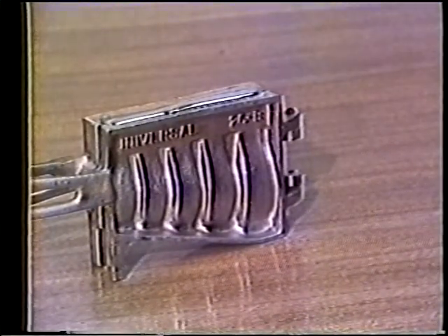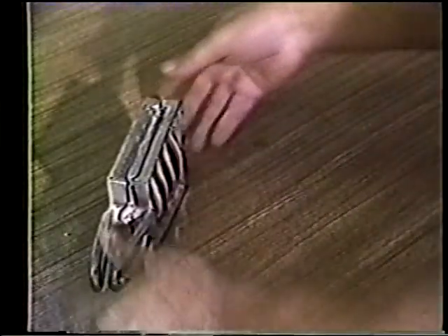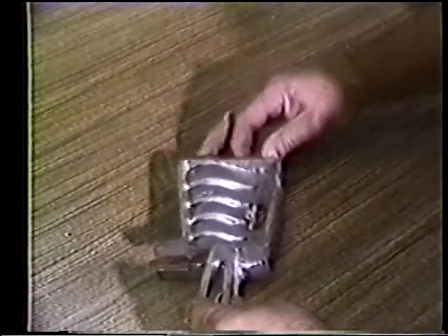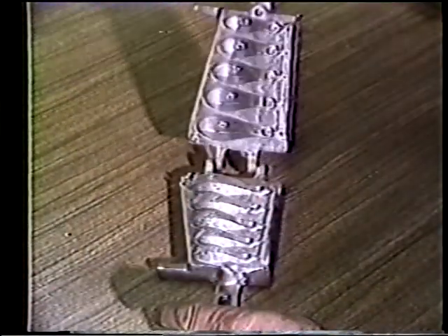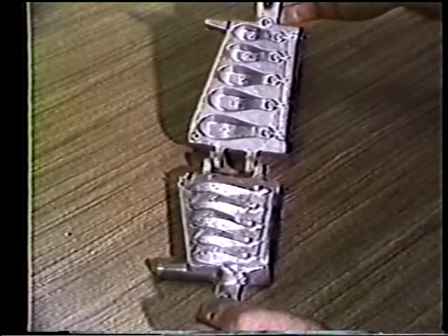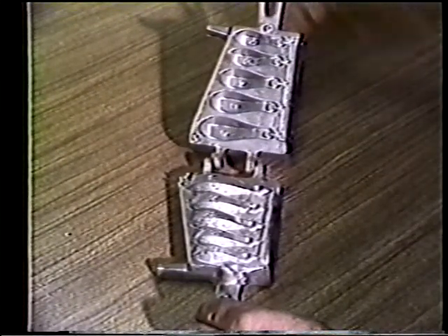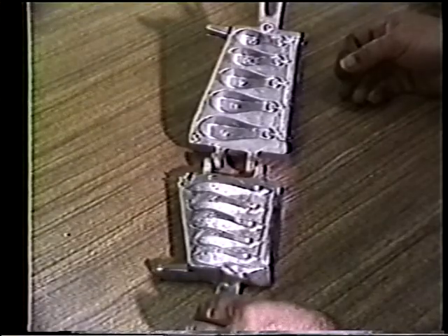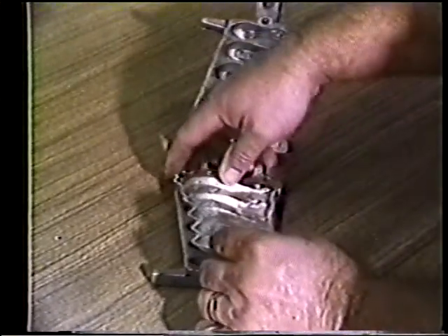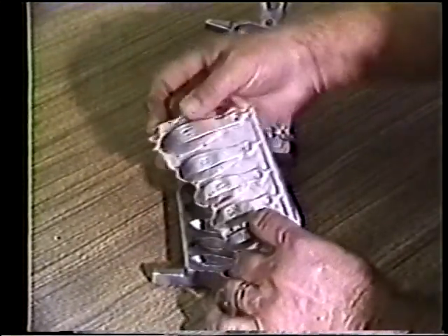The mold must also be in at least 2 pieces, and the pattern must be shaped so that the part can be withdrawn when the mold is opened. Die casting differs from permanent mold casting in that the metal is forced into the mold under pressure and held under pressure during solidification.